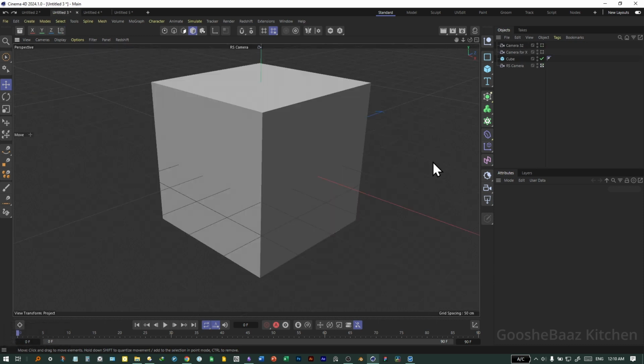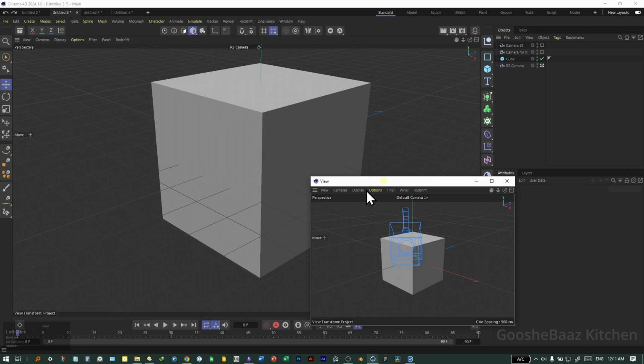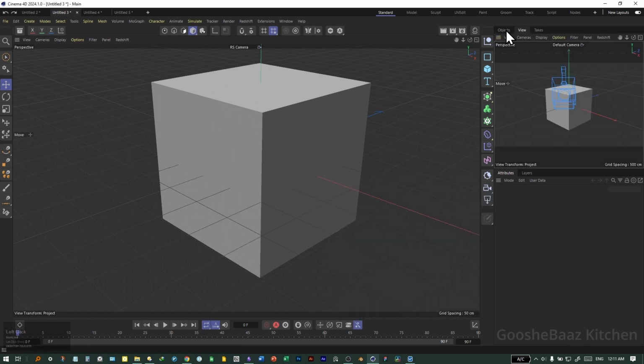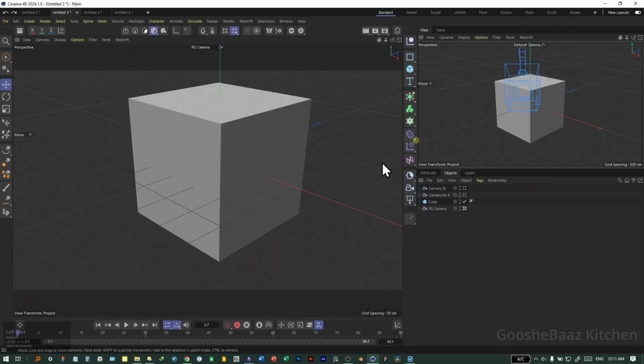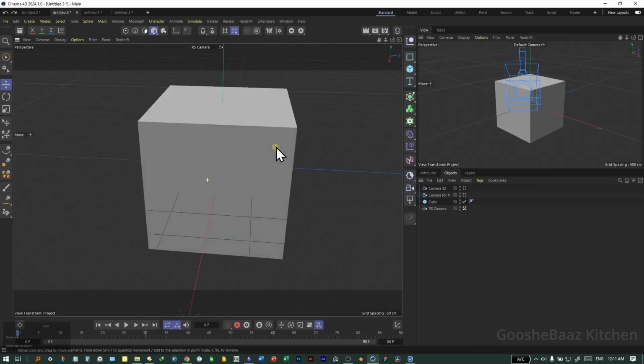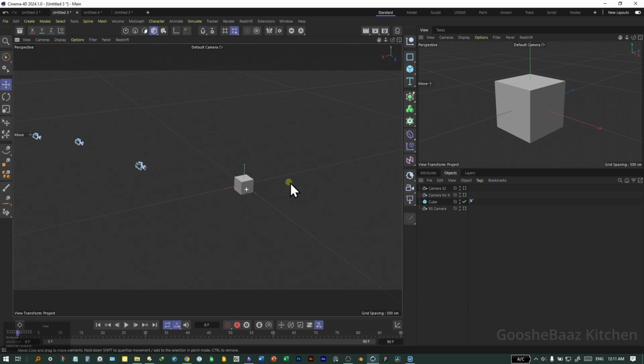So now let's add another viewport or view panel to manage and see what is really happening with the cameras and changing their position. Come here, Panel, Add New View Panel, change the size, grab it from this icon here, and put it here. Get back to the Object Manager, grab the object, put it down here, change the size here. Okay. Now I have two views, one that I'm changing and orbiting around, and one here.